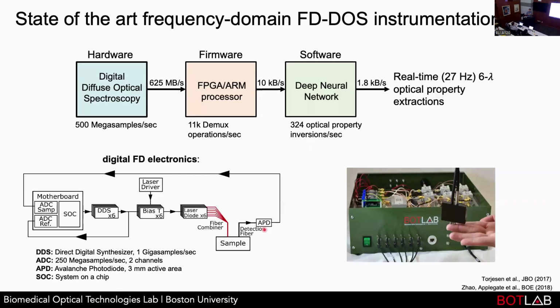One electron actually causes two electrons to stimulate four electrons in this avalanche-like process that provides intrinsic gain, a gain of about 100, which allows you to measure much lower intensity signals. And we need this because the light intensity for the frequency domain is very challenging, more than CW, since you're not integrating, you're measuring just at a single modulation frequency. You don't have that many photons to deal with. You need a very sensitive detector.